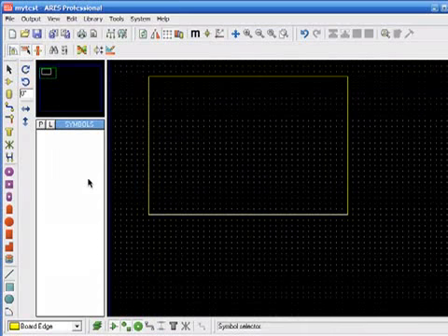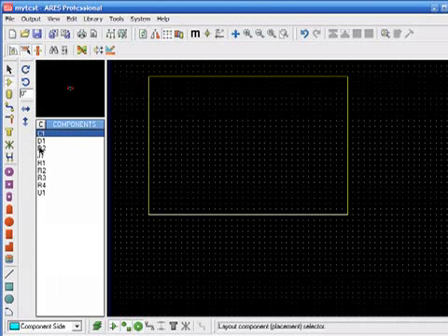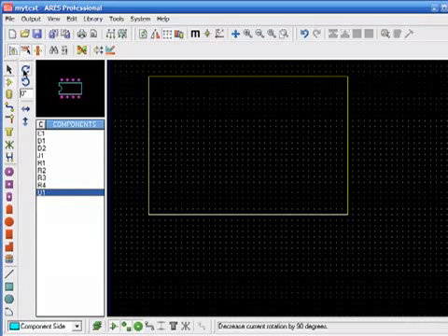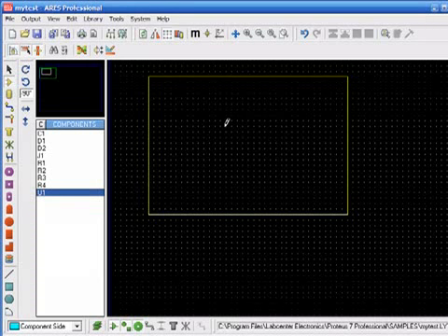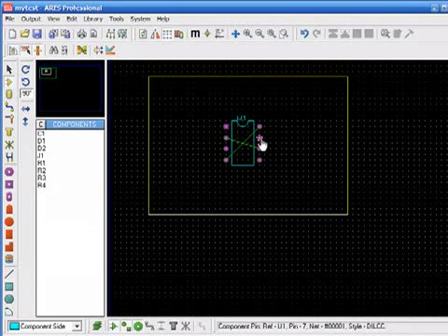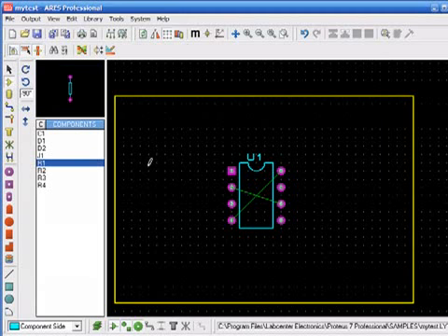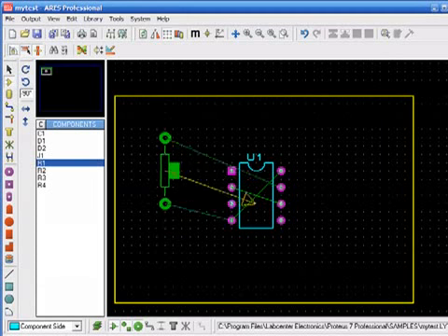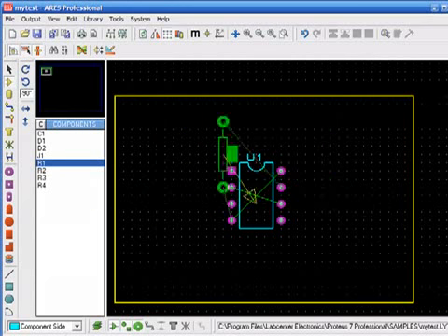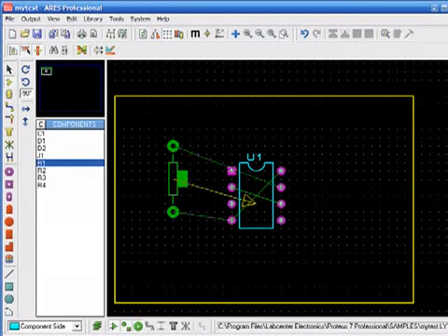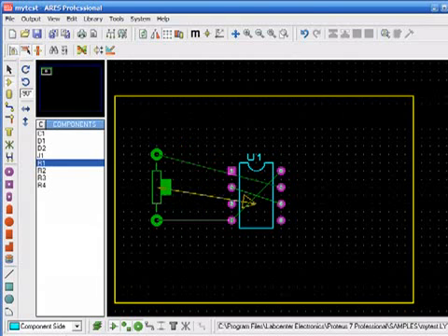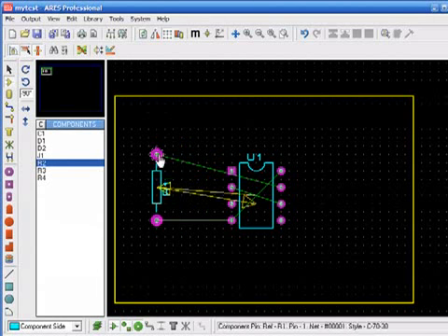This should do just fine for our design. Maybe it's too big, we can adjust it later. Then go to component mode, select the IC, rotate clockwise, click and then paste. It is similar to Isis. The green arrows show which pins are connected together, so that you can design it appropriately using Isis.